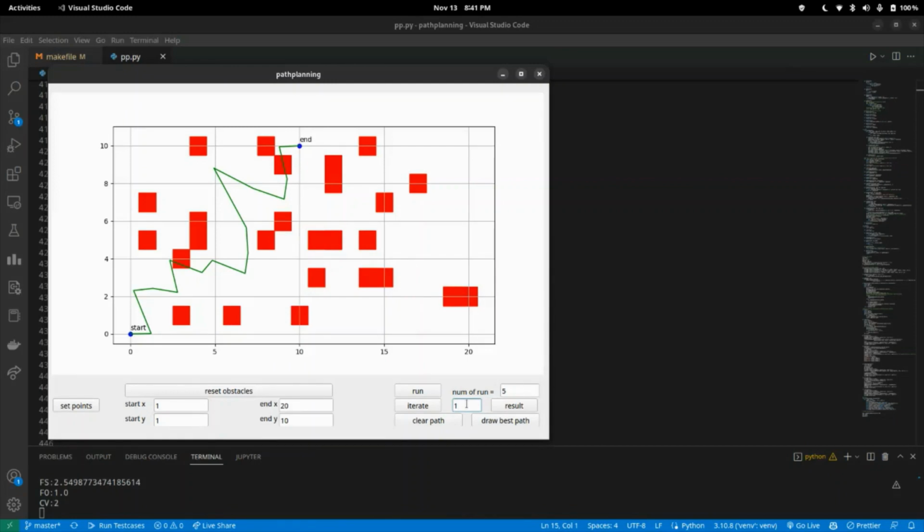So moving on, we increase the number of iterations and make it 20. Now we have a path which crosses only a single obstacle in the starting. And when we increase our number of iterations to say about 150, which is quite a huge number, we would get about a perfect path. And here we at last have a path which doesn't collide with any obstacle and is the shortest optimal path, which is derived at 150 iterations.